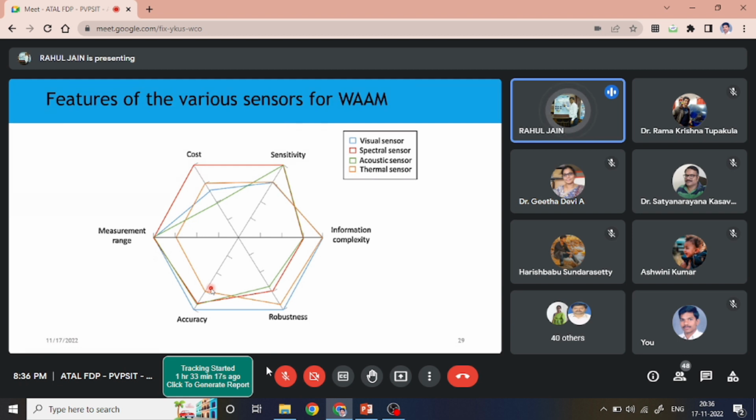This is not correct. Why? Because emissivity is a function of temperature, so if temperature is increasing, emissivity will also change. So you need to change the emissivity depending upon the temperature range. If you're not changing the emissivity with a change in temperature, then accuracy would be lost. The second problem is that emissivity is also a function of surface property, right? How much surface roughness is there, how much waviness is there, and all those things.